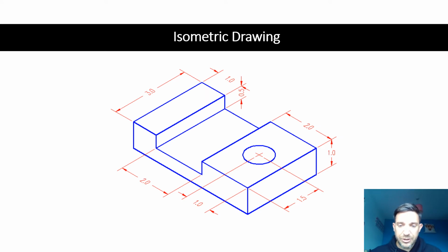So here is a picture of an engineered drawing in isometric. You can see here, we always start with a corner at the front. I'm just going to make that a little bit bigger. There we go. We start with a corner at the front. We project off 30 degrees each way, and we build our part up from that very first vertical line.